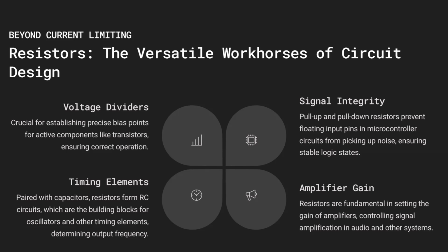Exactly. Unpredictable logic states. The pull-up or pull-down resistor acts like a tether. It weakly connects that input to either the power rail or to ground, ensuring the pin is always in a known state.